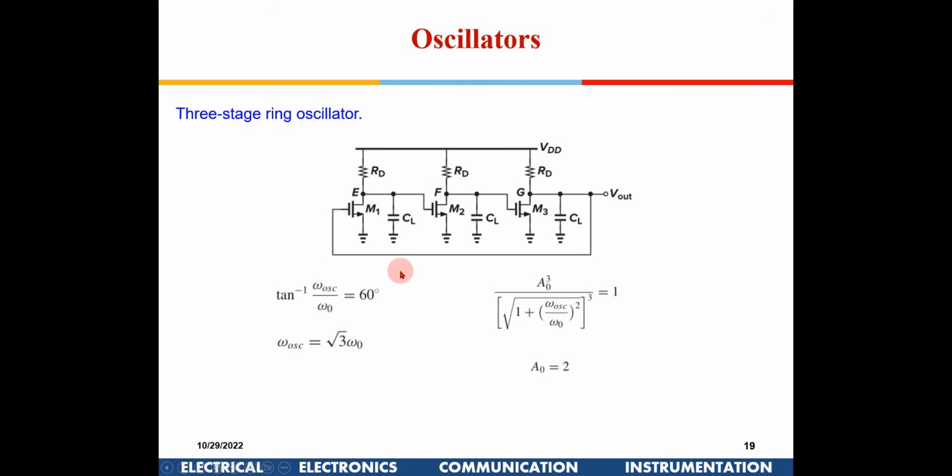Then as it keeps moving, it will keep getting amplified. So for our desired frequency, we can assume that noise of that particular frequency will be available. Say I am designing this for 100 kilohertz. So 100 kilohertz noise will be there. That will get amplified and keep growing. All other frequencies will not get amplified. Either the gain will be less than 1, or if the gain is more, the phase will be off. So all those other noise components will be suppressed.